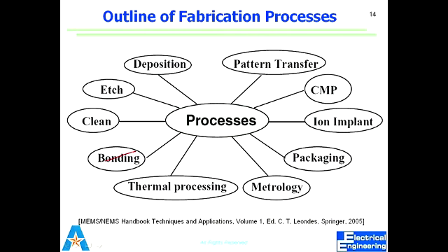That we have this mask set made by a VLSI designer who has placed all the devices where they're supposed to go, and he has placed different layers of devices on different masks, because in one case I might have to just do this, what you call doping, to make it electrically active. In another mask set, I will have to open these windows for electrical connection with the outside world. In another mask, I will then have to make this metal deposition. So define patterns where metal should go, right? So that mask set is, when I say set, it's not just one of those, there are multiple of those.